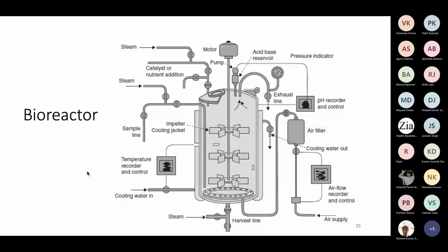Similarly, when you supply more amount of oxygen, gas holdup will increase. Amount of gas present in the liquid in the reactor system will increase. And if you have really very excess amount of air or gas, then you will have flooding of the reactor. And it is very much possible that it will actually push all the liquid to the outlet and you will have excessive loss. So you have to monitor all this parameter and then you have to keep all other operation parameter within the limit to avoid any failure of the reactor.